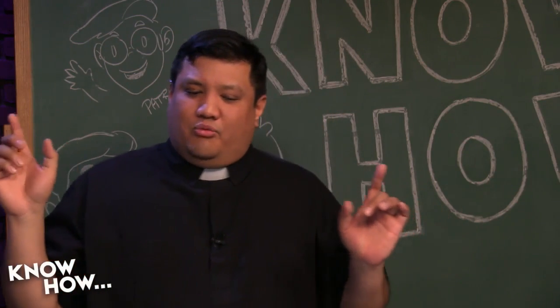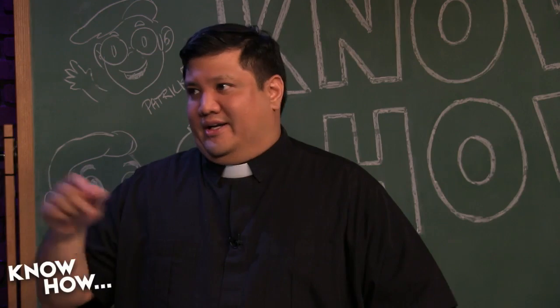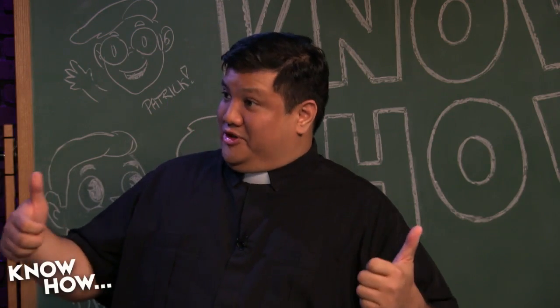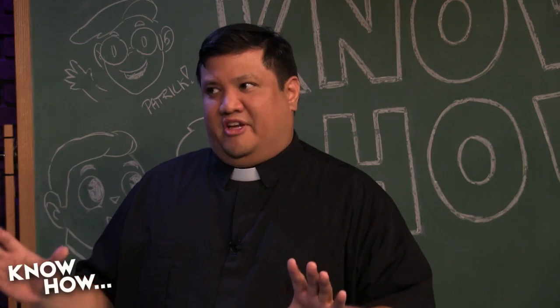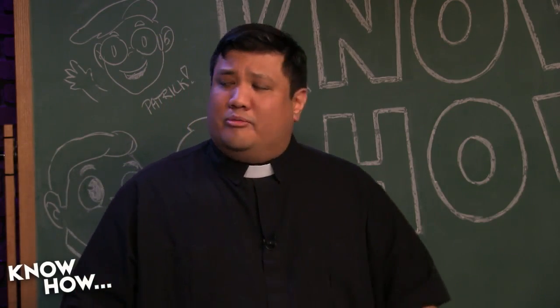Well, what did I tell you? What's the one time that you cannot combine 2 I2C devices? When they have the same address. Right, and they don't. So we should be good then. We do have to make sure that there's enough power because we're still running everything off the Arduino. But that's not a problem. We're going to get back to that in just a second. But first, we have to listen to these messages.